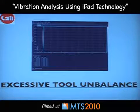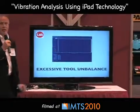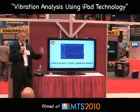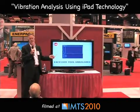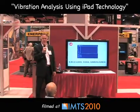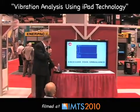Here's another one that I mentioned earlier that, okay, we have no bearing frequencies, everything looks good, no misalignment problems. We just have a high imbalance spike. This is indicative of somebody applied something to a motor, a spindle, or any machine that we're running that was unbalanced. We can quickly cure this problem by either balancing the unit or putting a balanced tool or pulley back on the rotating component.